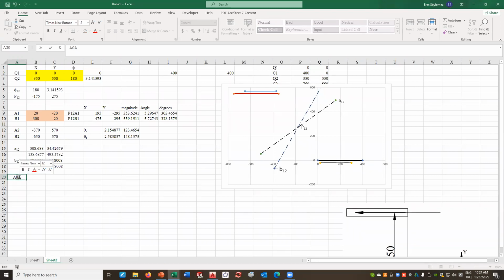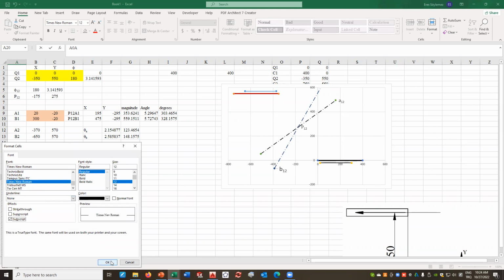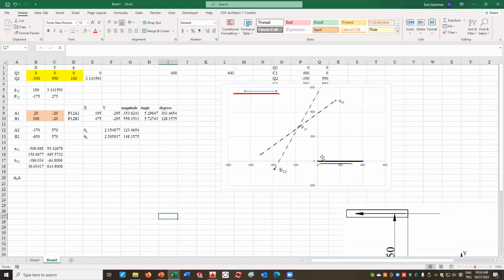Keep in mind that this A0A length has to intersect that perpendicular bisector. If I select it as 200 units, for example, this is A12, I don't think I will be able to reach that. So I will select it as, shall I say, 400? Let me repeat, you cannot select anything, because if it does not intersect the perpendicular bisector A12, there is no solution.